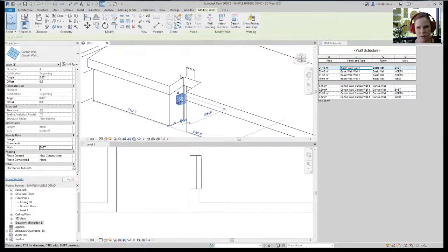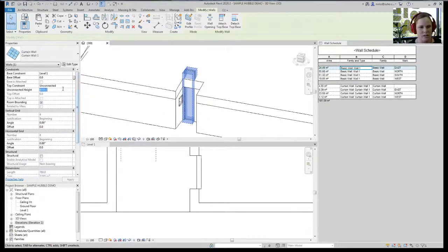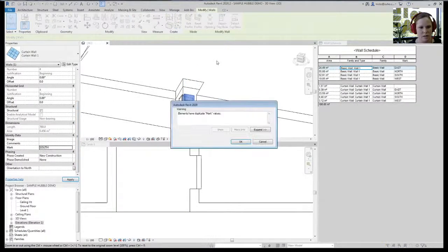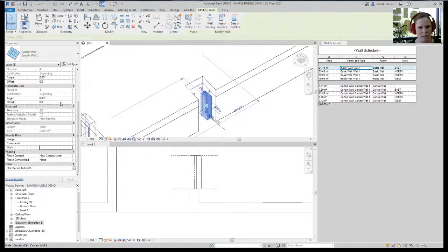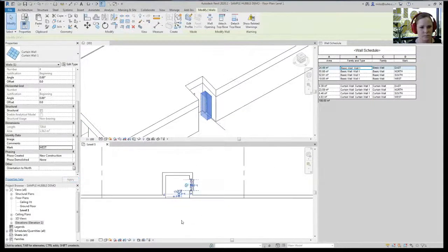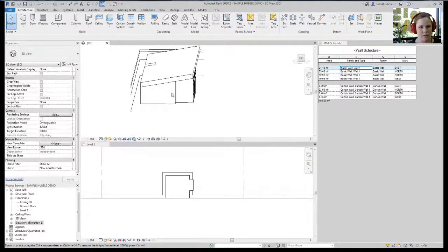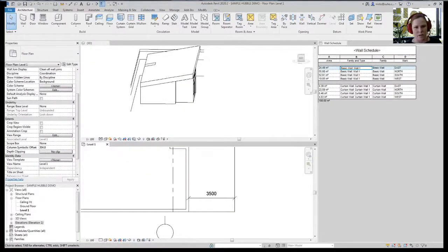So now we have another curtain wall appearing in that table that is east facing. Do the same on this one. 600, 1500, which is 2100 head height. This one is facing south. Don't have much south facing on here on purpose. Okay, this one is western facing. Good. Okay, so there's nothing else along that south boundary, because in this particular instance there's another house there. It's a boundary wall.